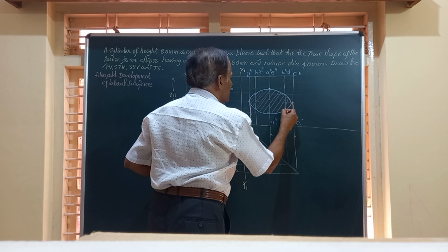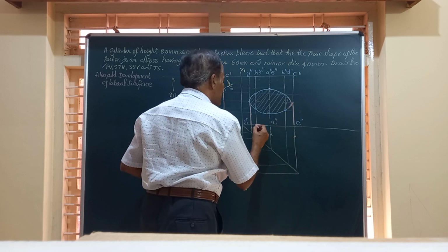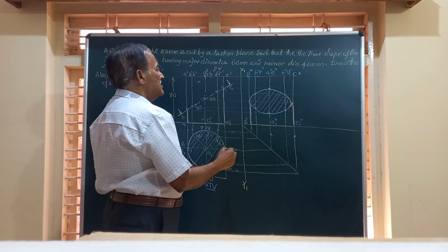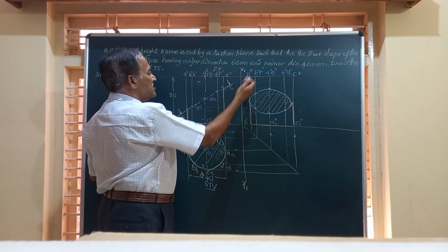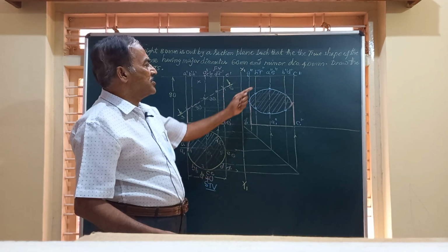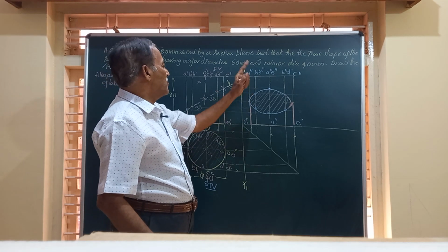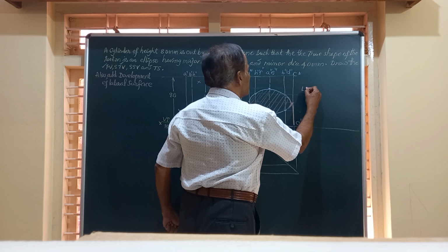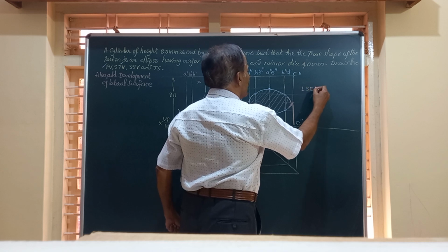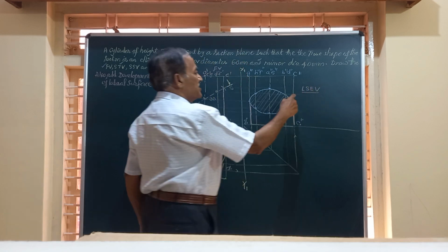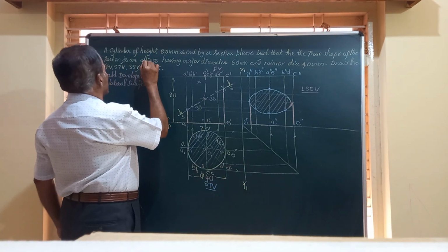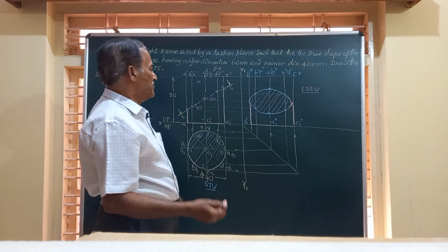dark lines. So this is how it will appear, friends. The base of the solid is intact, so I have to show like this. Friends, the portion above this is now removed, so we don't have anything above this. So friends, this will give you the left sectional end view, LSEV, left sectional end view or left sectional side view, or SSV, sectional side view you have got.